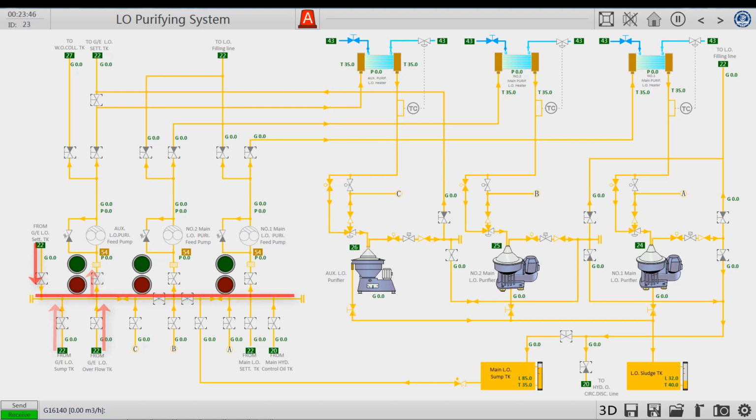In fact, these 3 channels of oil were introduced in the service system. Each oil tank has a relevant oil circuit. They can be transported to the oil separator for purification. Select the source of the oil by opening these 3 valves. After passing through the filter and the oil feeding pump, the lubricating oil will divide into 2 paths at the node.